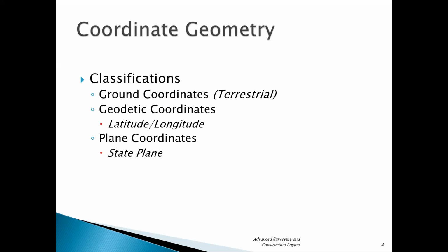In general, though, we're going to be talking about what we call plane coordinates. That allows us to use Euclidean type geometry, planar geometry. We don't have to worry about the spherical aspect of anything, especially because our projects are very small. Now, people that do deal with very large projects like highways, if you're dealing with highway calculations that start in Cincinnati and go to Dayton, you have to deal with curvature. You can't just talk about one unique plane, so that does get into other aspects. We're not going to be dealing with that. We're going to keep everything really localized, a very simple plane.